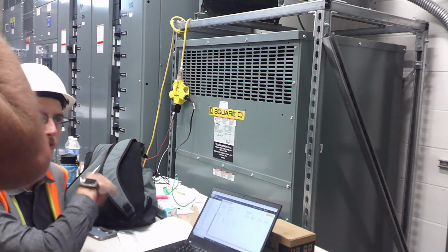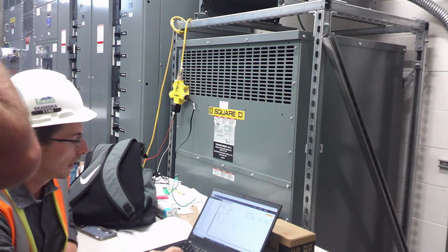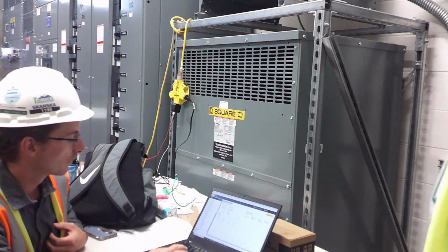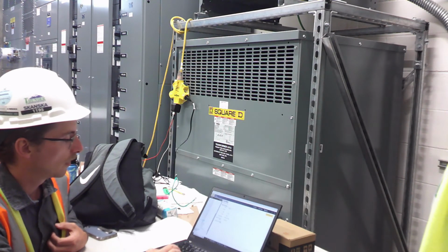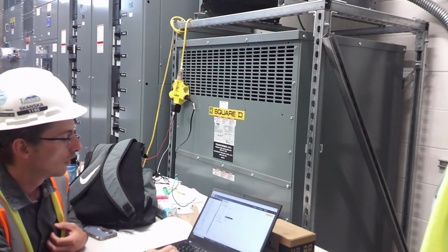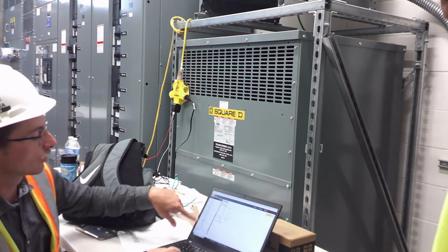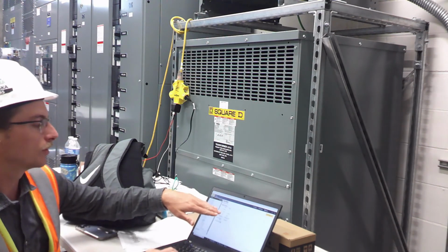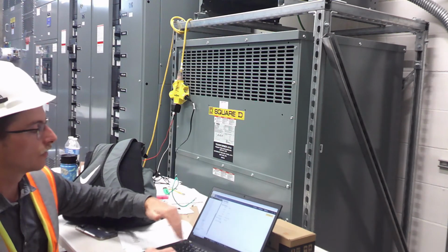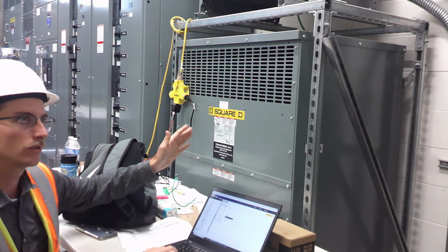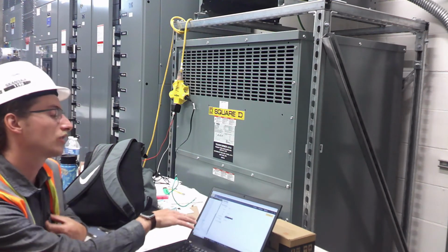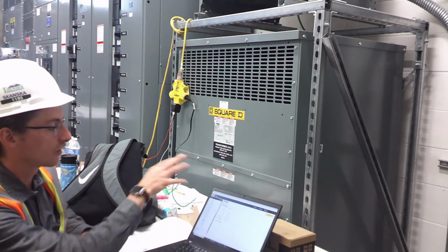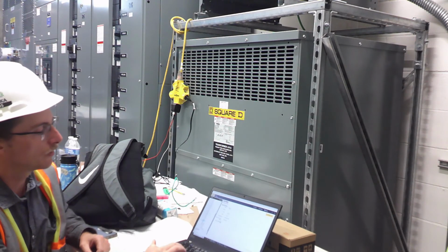Before we started the training, I hit discover. This controller hadn't been commissioned onto its area and zone yet, so it's showing up here down on the list. So I'm going to click the bridge, and then I'm going to select what. Normally, there's already a few devices under this bridge in the zone, so it's not letting me change it. But normally it would give you the whole list of all the areas, and then once you select the area, it'll give you the list of all the zones. That's if it's a bridge that hasn't been put into any area or zone yet. Since this bridge has already been put into that zone, it's just locking it into that one.